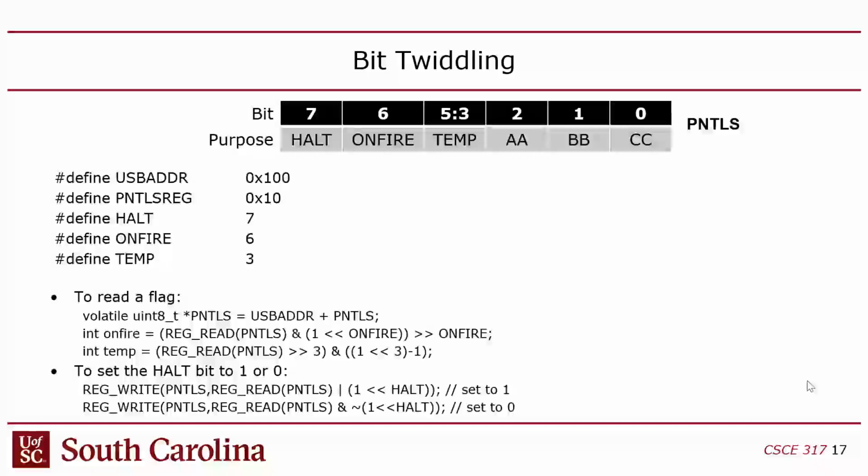So the way that's done, and I don't actually know how the ESP32 does it, but on the FPGA boards that we use in 313 and 611, or at least I should say on the Nios processor that we put on those FPGA boards, there's a special variant of the load and store instruction for doing I/O. They have load IO and store IO. The purpose of those is to bypass the cache, right? But how does the compiler know you want it to generate the load IO versus the load instruction? Generally, it knows that through this thing called volatile.